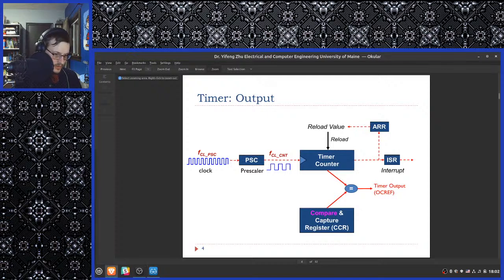Do all timers have a prescaler? I'm going to assume so, yep. Well, the crystal oscillator itself obviously doesn't, but yeah, all timers have a prescaler. Isn't the prescaler software? If that fails, wouldn't the timer get messed up? No, the prescaler is also hardware. The prescaler is a hardware component, but it is configurable by the software.